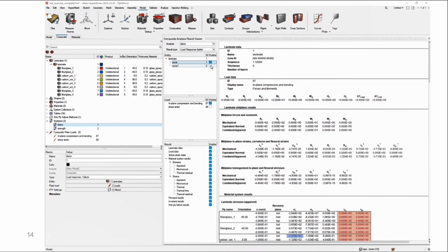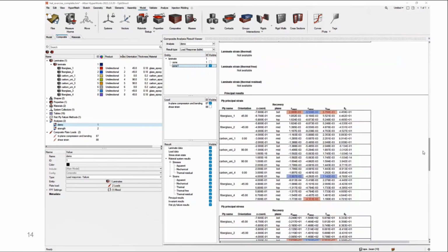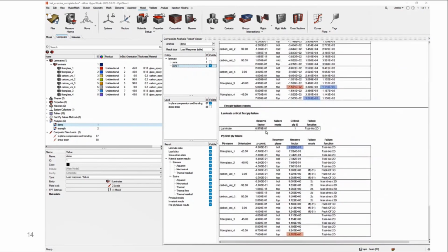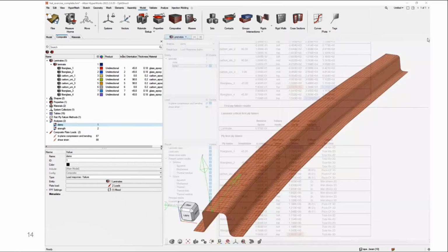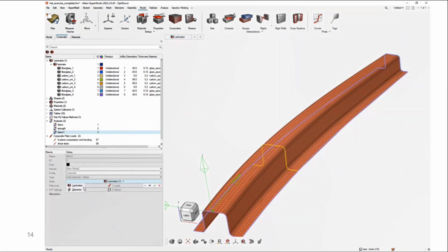So our laminate has two zones on our head here, and we can see the laminate with plus minus 45, twice 0, minus plus 45. So that's one part of this complete laminate, and also the complete one in the second step. Now, when I look at the reserve factor, in this case I get roughly 0.7. Now, just for comparison, and that is actually quite a drastic change, as we'll see now.